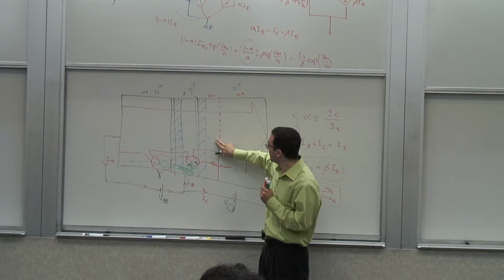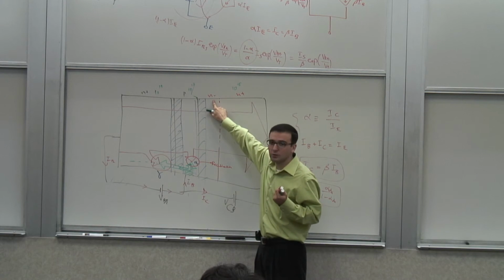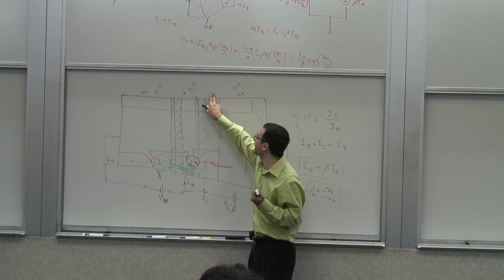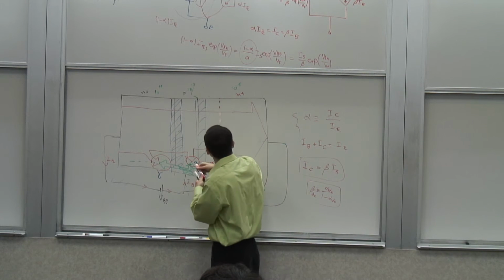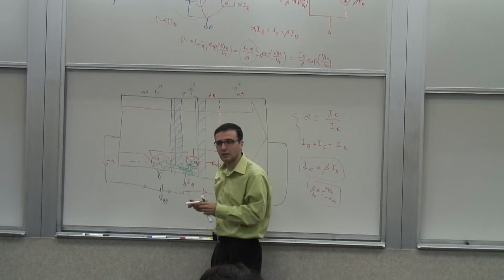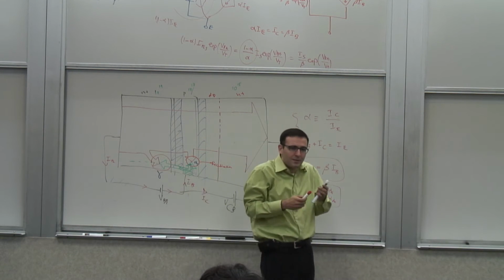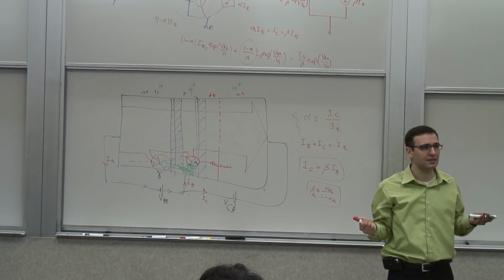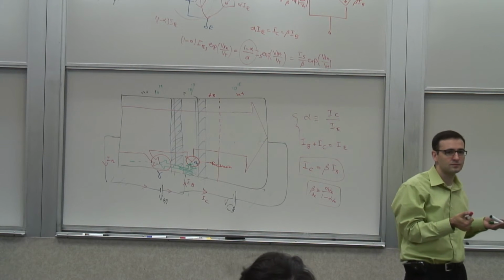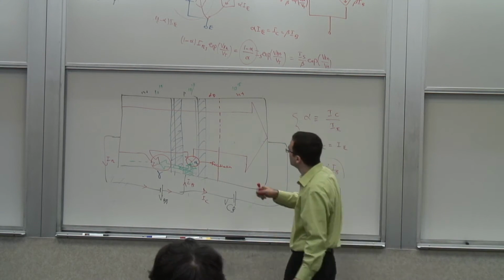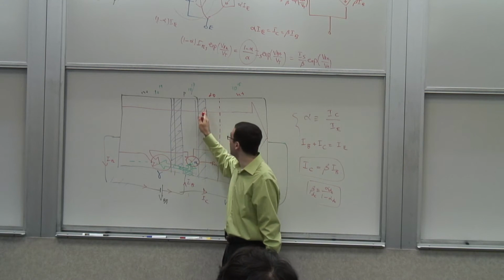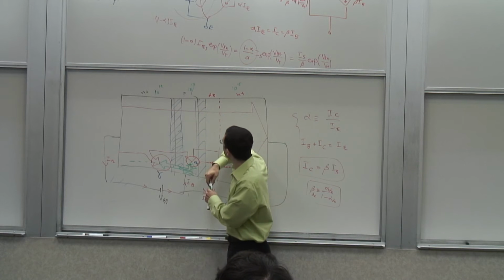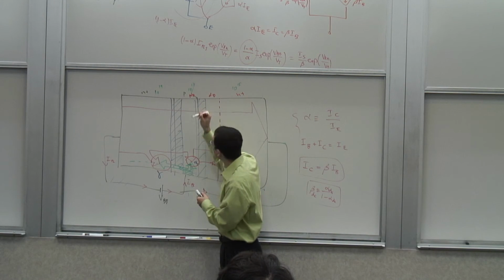So what do I need to do? Well, really, it boils down to being able to have a larger N, or more accurately, ND, the doping level. I want to be able to use a higher doping level. But we just saw that that's conflicting with the reduction in the Early effect, because we wanted this to be low so the Early effect is low. But what I need is for ND to be lower than NA, right?